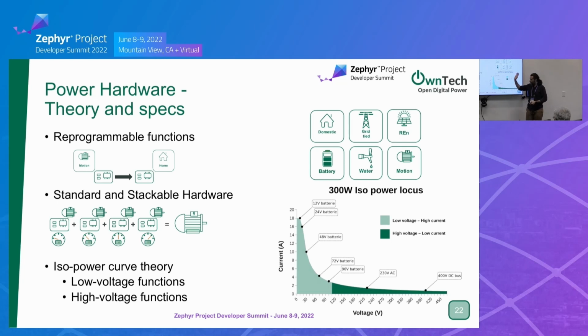So you have to find a place where you cut this, and you decide where you want to operate on the low voltage and where you want to operate on the high voltage. We decided to cut at 100 volts, and we designed a board that can operate below 110, 120 volts, and learn all we can with it so we can design the board that's going to operate on the high voltage side as well.